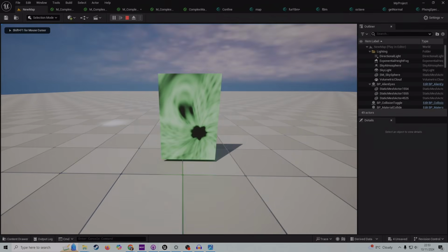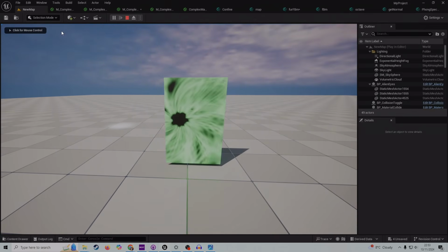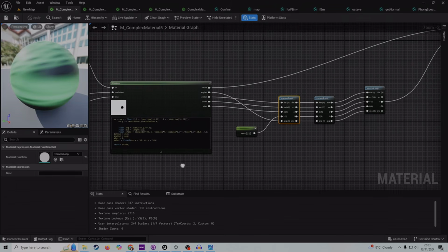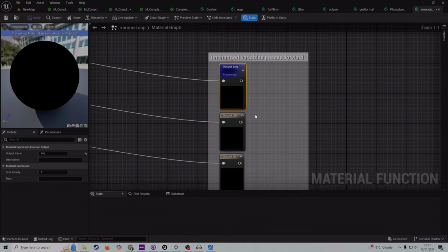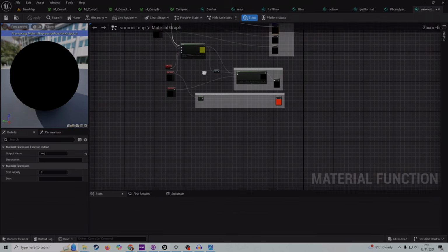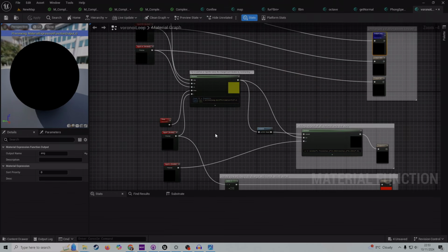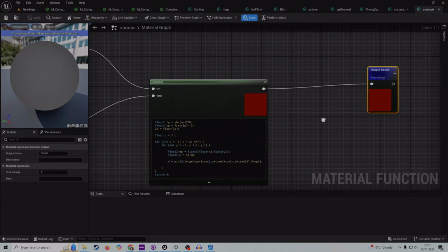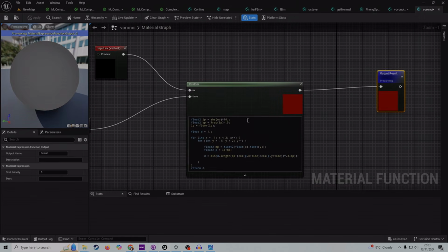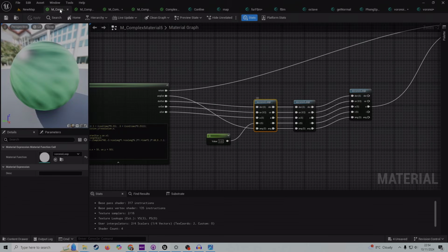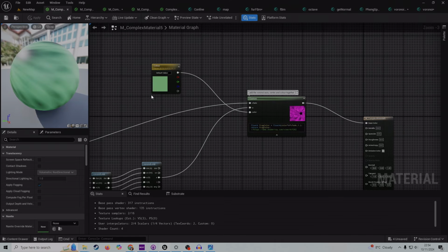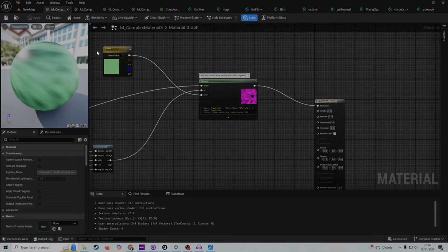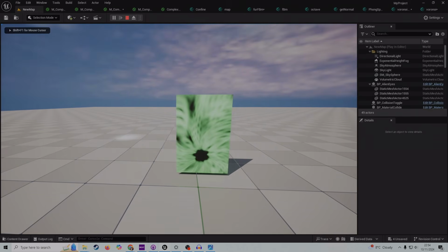And essentially what this is, is a Voronoi loop. I'm creating this center here, which is the C fade, and then this Voronoi loop basically loops different boxes together so they combine together. The Voronoi code here takes in the UV, changes it. That gets looped over, so there's 3 octaves there, and then it gets combined together with the color to create this thing here.